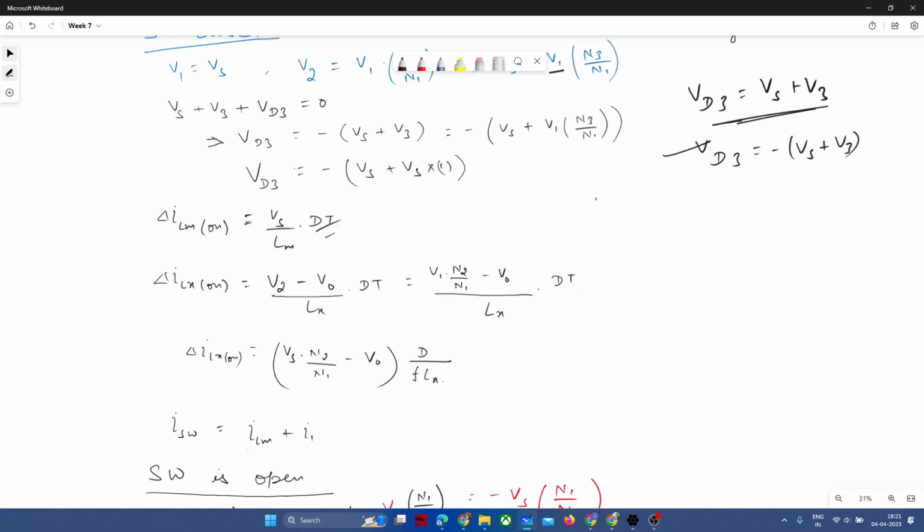You will have to eliminate heavier materials and try to achieve it with lighter materials. So that's another reason. At the cost of weight, since you have eliminated the core, you will have to plug in a higher magnitude of current in the air core. That has another advantage: your core will not get saturated, but it will require higher field intensity from your current source.